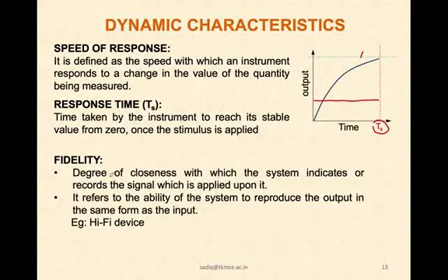Fidelity is another term. It is the degree of closeness with which the system indicates or records the signal which is applied on it. It also refers to the ability of a system to reproduce the output in the same form as the input. I will explain this. Take the case of a microphone: you are giving a sound, that is a signal. Are you sure that the microphone is picking the same signal as such, or is it losing something? If it is capable of recording the same output as such, it is a high fidelity instrument.